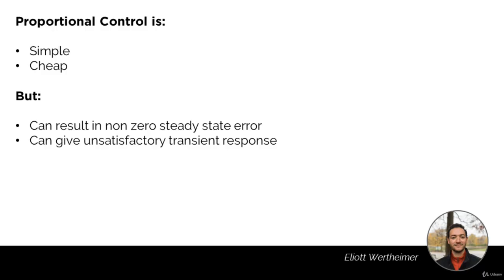So it leaves it lacking, but it's also the most simple way to implement a feedback control loop, or a closed loop control. If you were to compare it to a mechanical component, a proportional controller is actually a spring. If the error is too large, it will immediately pull back on it to make it smaller. But if the error is too small, then the spring will barely move and won't be able to compensate for that error.